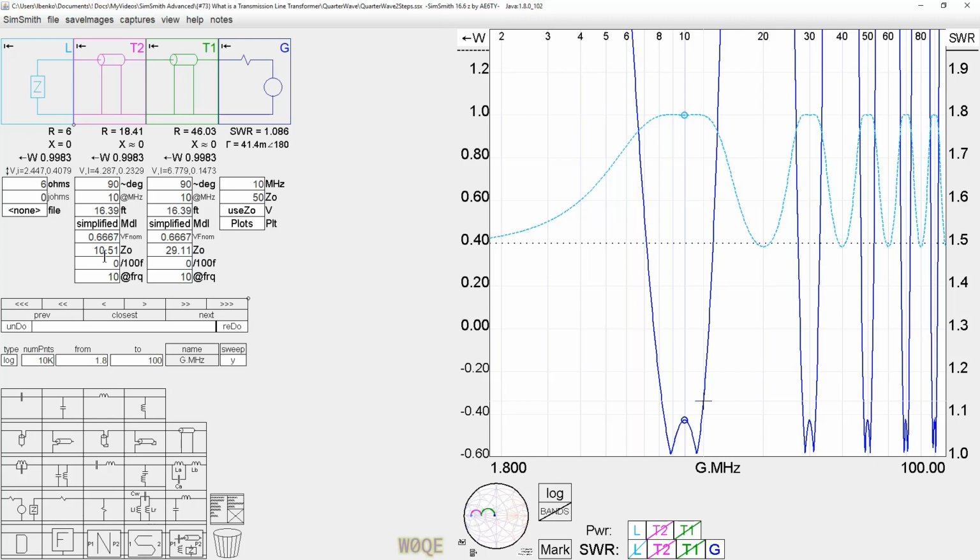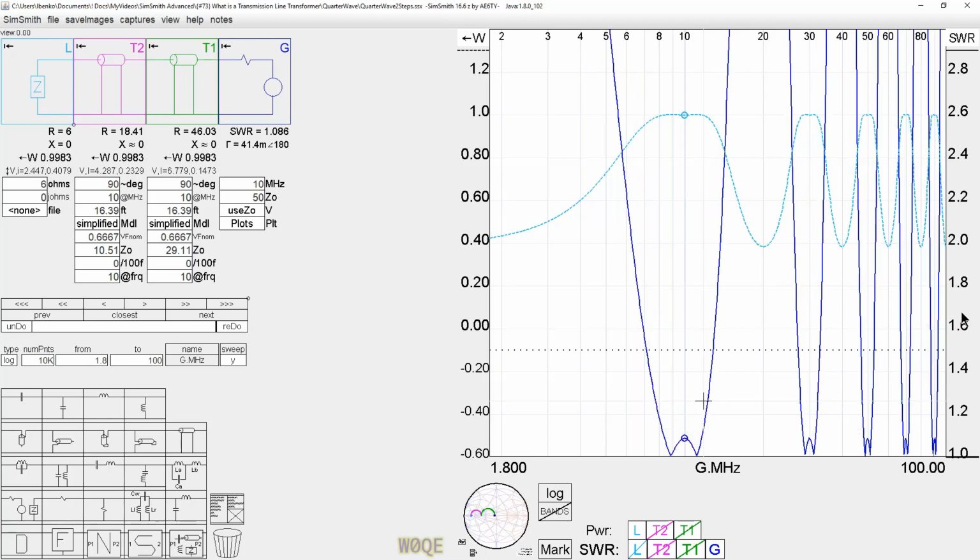There's some formulas that tell you where to put these impedances, but basically you set the mean here to be the geometric mean of these two, and then you match to that point, and then from that mean to the final goal. But what we see here, let's make sure we're doing it the same way again. Okay, 1.5 to 1, and now we see that our range goes, instead of from 9 to 11 megahertz, from 7 to almost 13 megahertz, which is a big improvement.